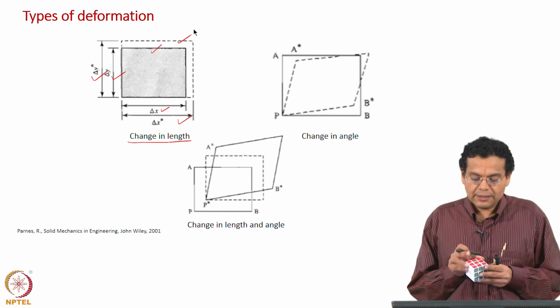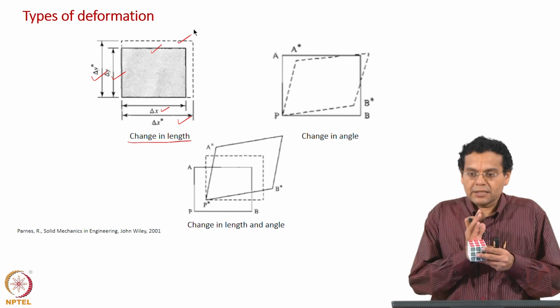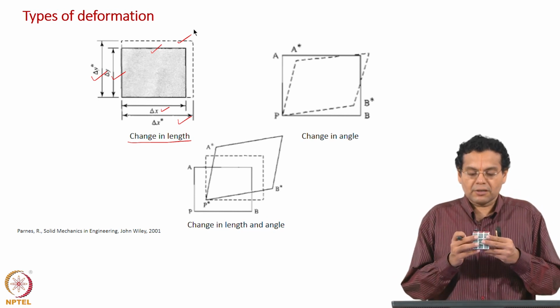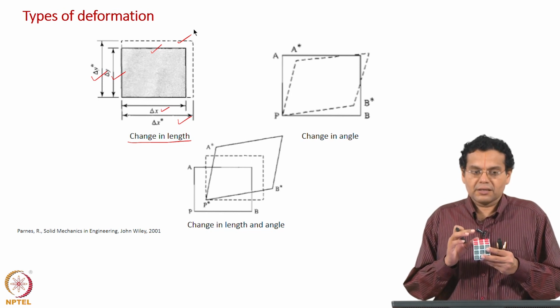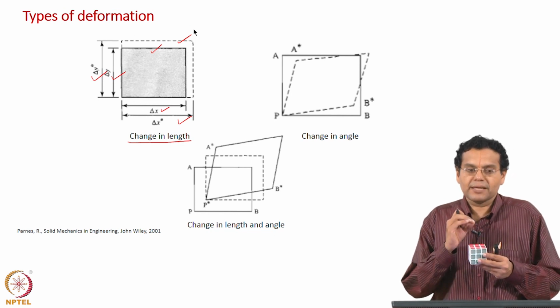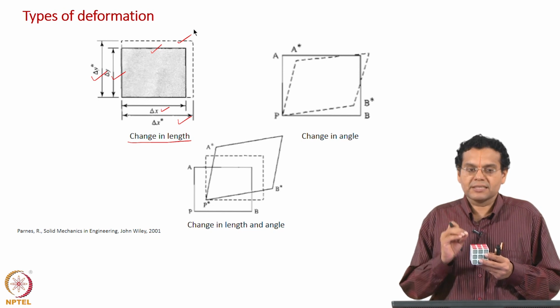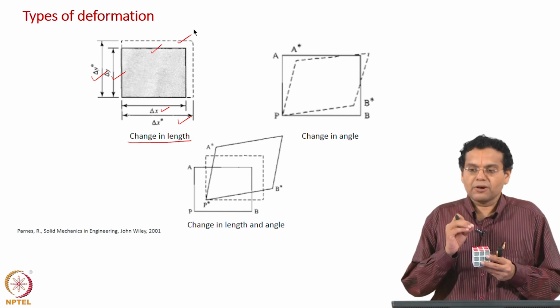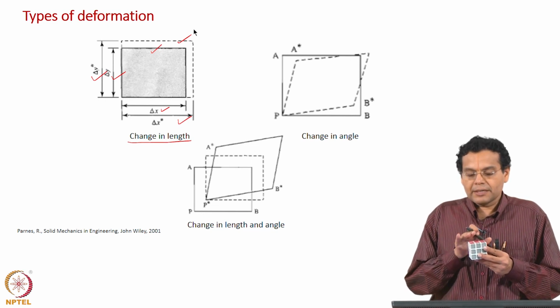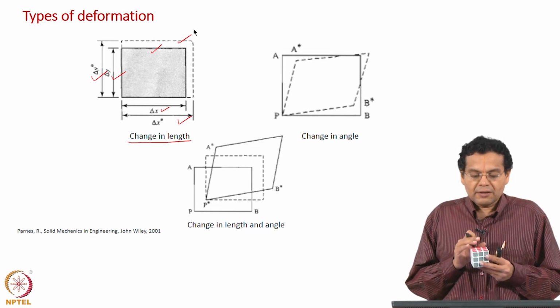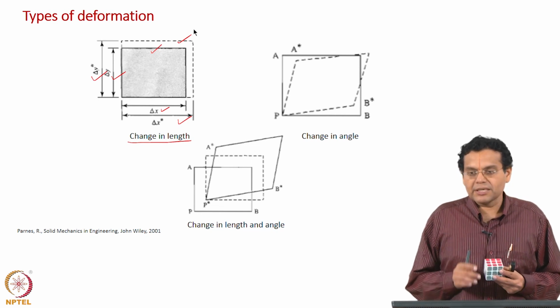In the case of a solid, it goes from one equilibrium state to another equilibrium state. I have a solid, and different names are given for the state before applying the force. We can call it the initial state or undeformed configuration. And when you apply a force, it undergoes deformation. What does deformation mean? For example, right now, change in length.